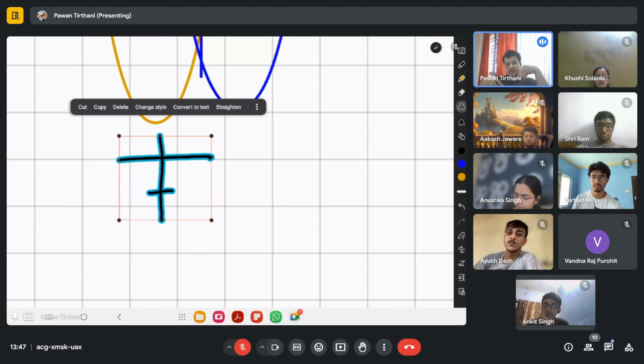What does my onboard aircraft do? I measure the depth of modulation of the 90 hertz and I compare it with the depth of modulation of 150 hertz. If the 90 hertz modulation is higher, more deep, or stronger, that means I'm on the left hand side.